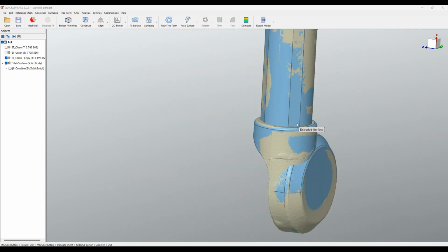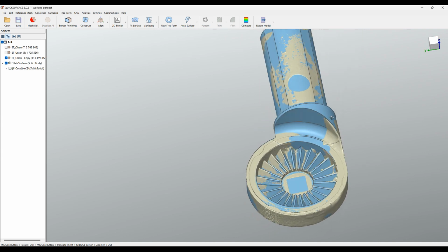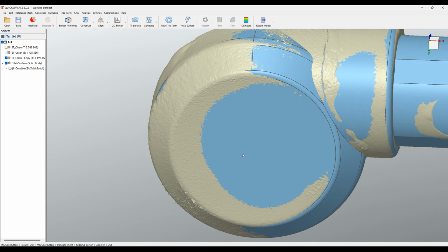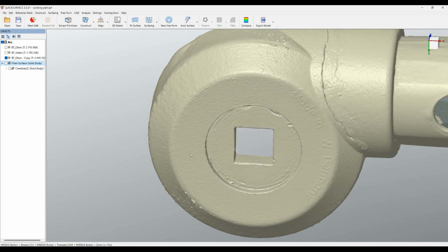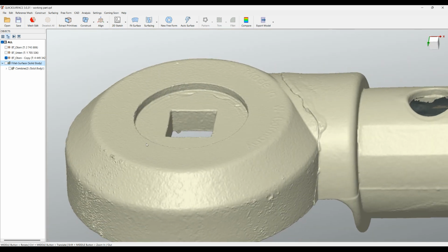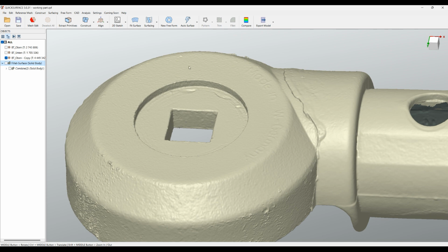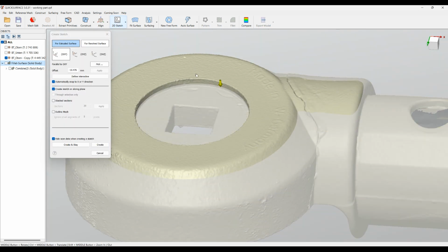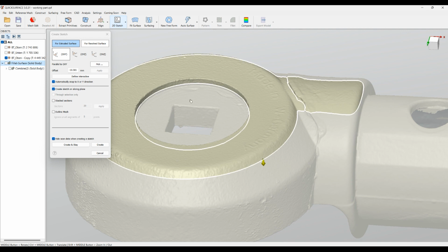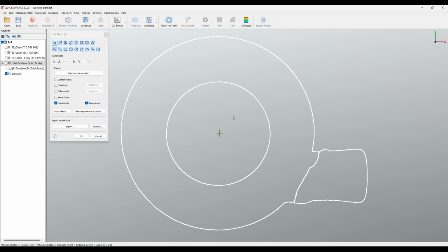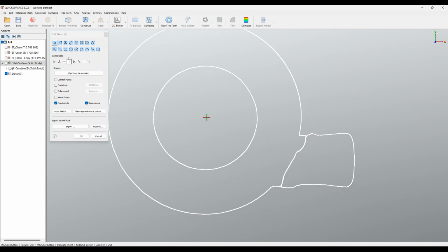So we are done with the most complex problems, to be honest. Now what we need to do is just to cut off from the base. How we can do this with, let's try it with this, another simple extrusion. I will just create a 2D sketch, just drag it to get this shape here, and we'll create my extruded sketch.